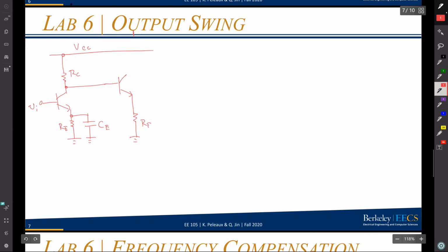I'll call this 3 and 4, so you know where this fits into your total amplifier design. The output, of course, for an emitter follower is taken at the emitter. We'll add a coupling capacitor here, which I can call CE4, and then we'll have our load resistance here. That's VO.